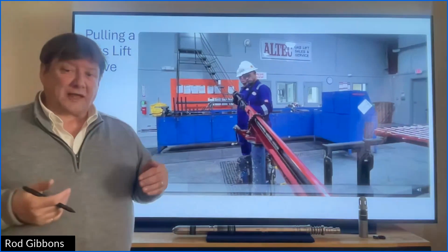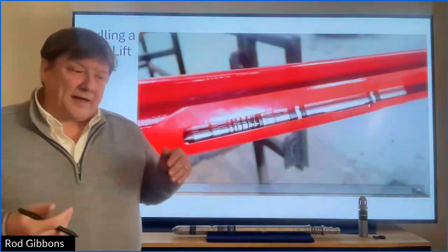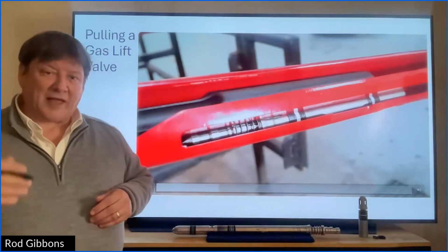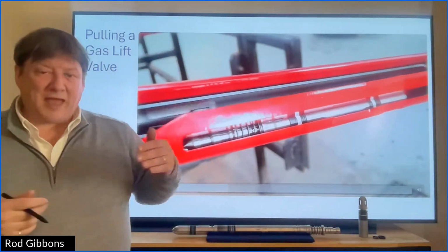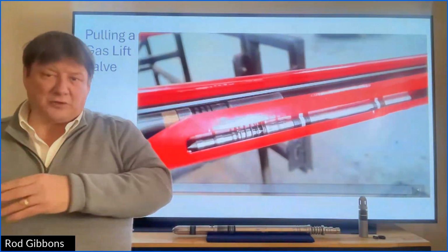What this also allows you to do, because it's designed this way, is that wells can have multiple gas lift valves in them. You can run past one and go down to a deeper gas lift valve if that's the one you want to pull, if that's the one that's causing problems.